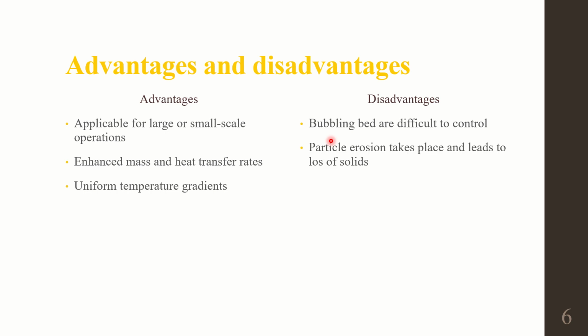The second one is that particle erosion takes place and leads to loss of solids. In fluidized beds, since the particles also start to move, the particle-particle interaction is very high, and because of that, particles may collide with other particles and with the walls. This leads to erosion of the particles, wherein particle loss occurs.